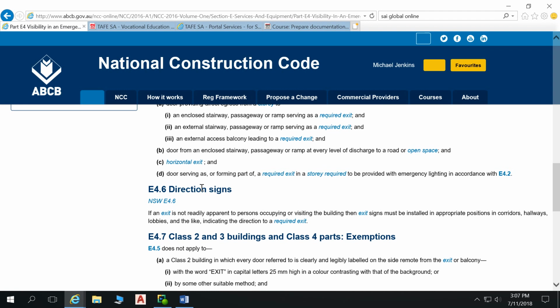And then of course, as with all things on these plans, you say exit signage to comply with AS 2293 Part 1. So it covers all the luminance and so on, and the requirements around battery backups and all that sort of stuff, because of course we can't just have exit signage which is just hardwired in with no battery backup, because if we have a fire, the first thing to go out is the power. We want those exit signs to be visible in the event of that blackout. So that's all the fire safety requirements covered.